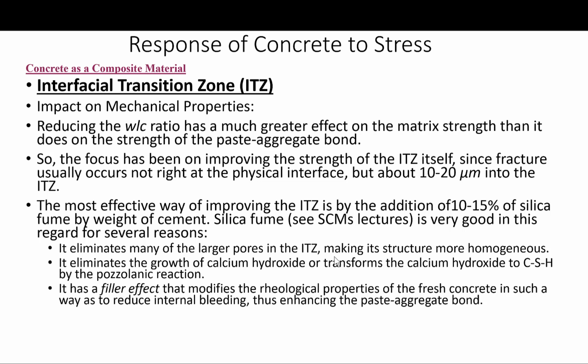However, for high performance systems, such as high strength concretes above 100 MPa, high strength fiber reinforced systems, or systems containing special aggregates such as graded stainless steel aggregate, high bond strengths resulting from the improvement in the properties of the ITZ appear to be more important if the full potential of these special materials is attained.